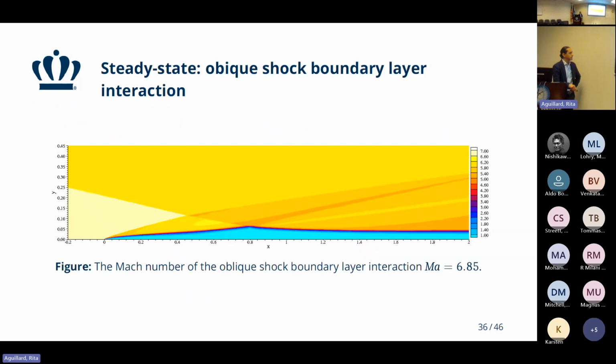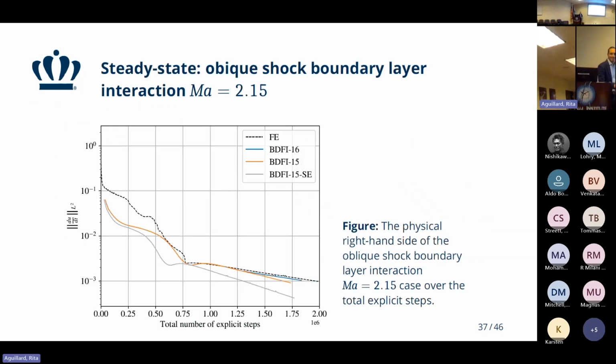But yeah, I can imagine that this plot is very dependent on this. It could, but it's a balance. You need to make sure you converge in dual time. So I could try 10 to the minus 7, maybe I win a little bit more. But what happens at the end is that the scheme starts to behave similar to an explicit scheme in a way, at least for this case.